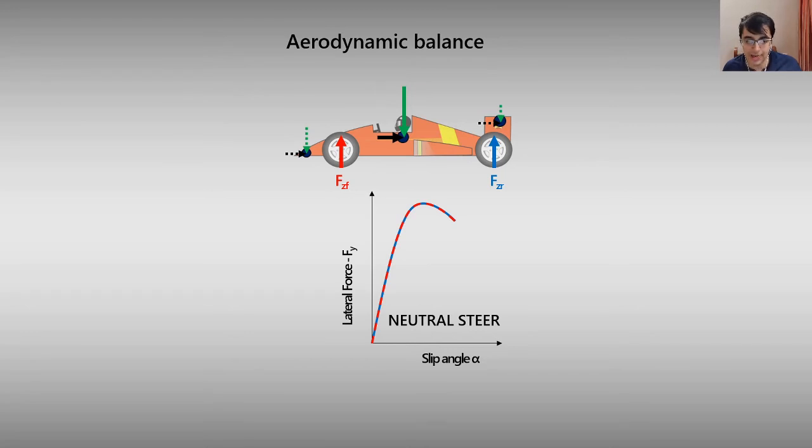Slip angle is basically an angle that's generated because the tire shears with respect to the ground. Again, I won't get to the details of this. We can cover this in maybe another episode on vehicle dynamics. But a higher slip angle means that your car generates more lateral force. Now what aerodynamics does is it increases the cornering stiffness, which means that you can get more lateral force for a given slip angle. So even though the tire might have the same slip angle limit, at that limit, you can have higher load.